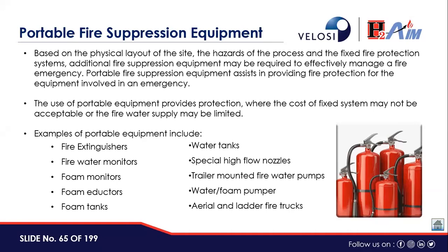Okay. Next question. For a hydrocarbon pump station, what type of fire extinguisher would you advise to position there? See, in general, for the pump areas, if they are operating at high temperature, a water sprinkler system or Deluge system is installed, supported by manual fire extinguisher systems through powder, because the foam system is generally not so effective on the pumps.